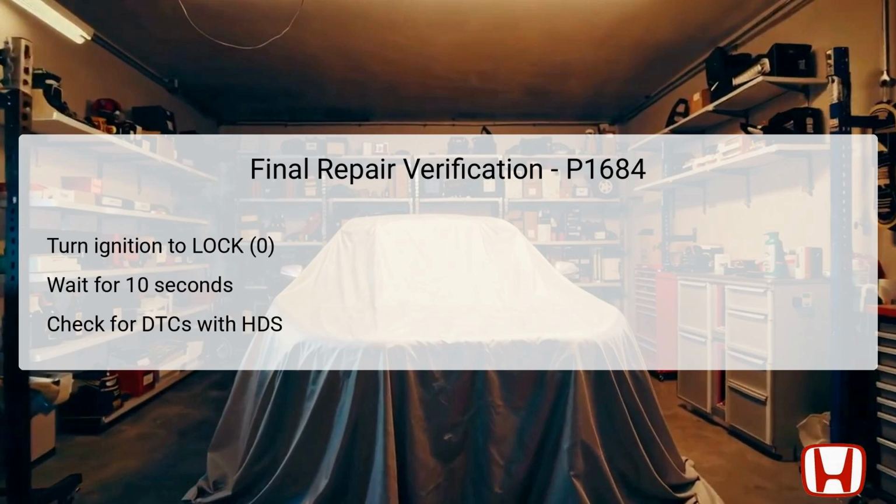Finalizing the troubleshooting process requires the technician to turn the ignition switch to the lock, 0 position, and wait for 10 seconds before starting the verification checks. This brief waiting period allows the vehicle systems to reset. After 10 seconds, the technician will again turn the ignition to on, 2. With the HDS, the technician should check for any pending or confirmed DTCs.